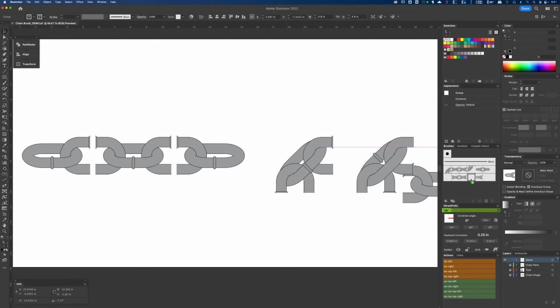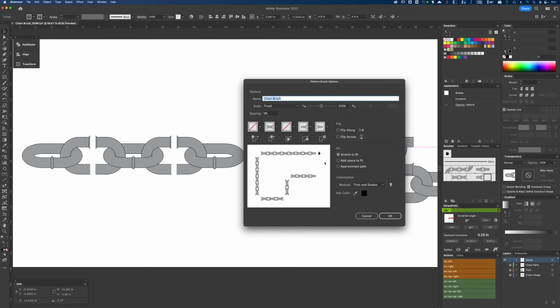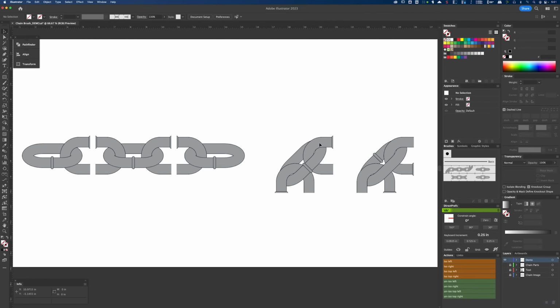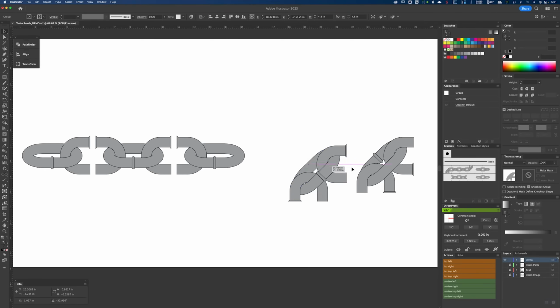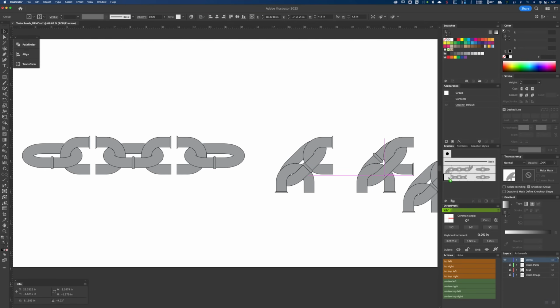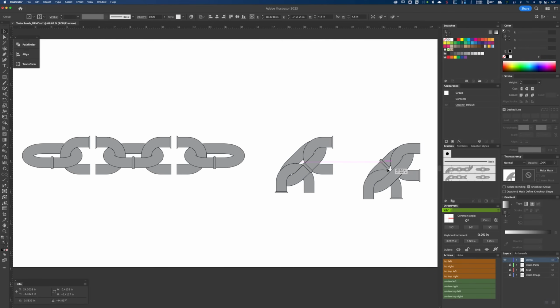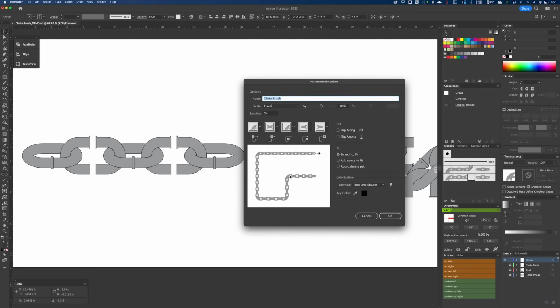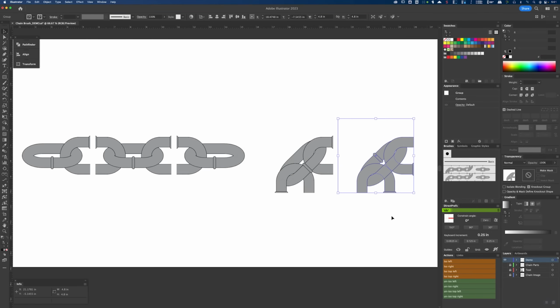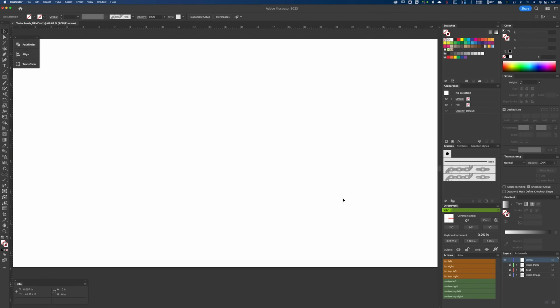And then I'm going to add my other end cap. And again, press Alt or Option, and then drag that to the very end. And again, you'll see a preview up here. Hit OK. And then lastly, we'll drag our outer corner into this first box here. And then you'll see a preview of it at these 3 corners. And then our inner corner goes in box number 4. And you'll see a preview right here. Then hit OK.